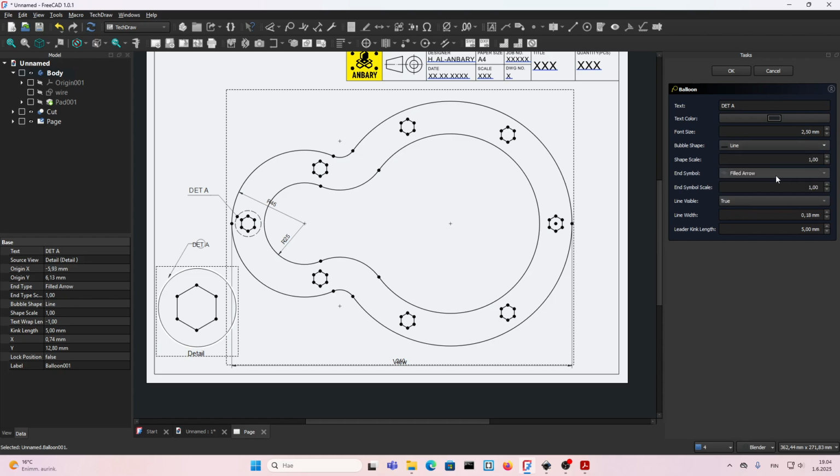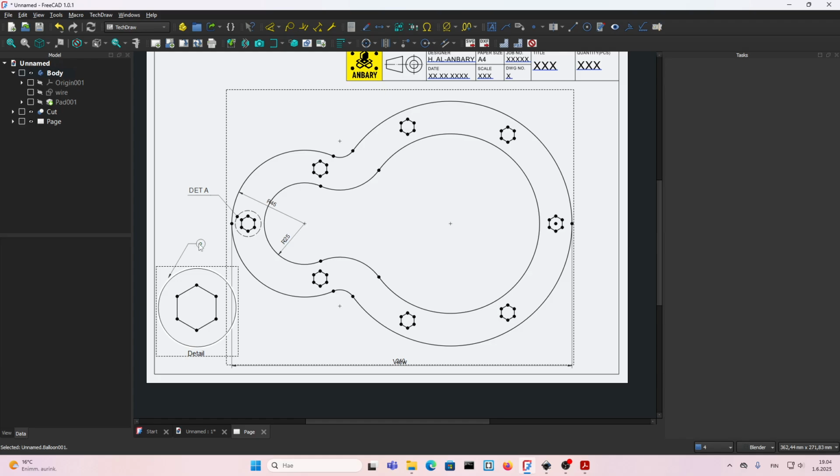Let's make a line under. Let's make it 3 millimeters. Let's make this false. Press. Now, as you can see, it didn't update for some reason. Let's see. It doesn't update. Sometimes this happens. So what you need to do, just delete it and do it again.